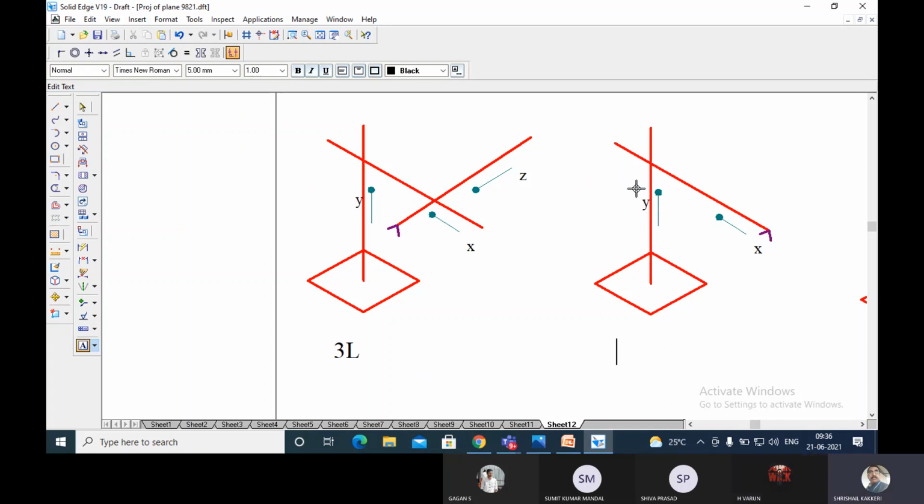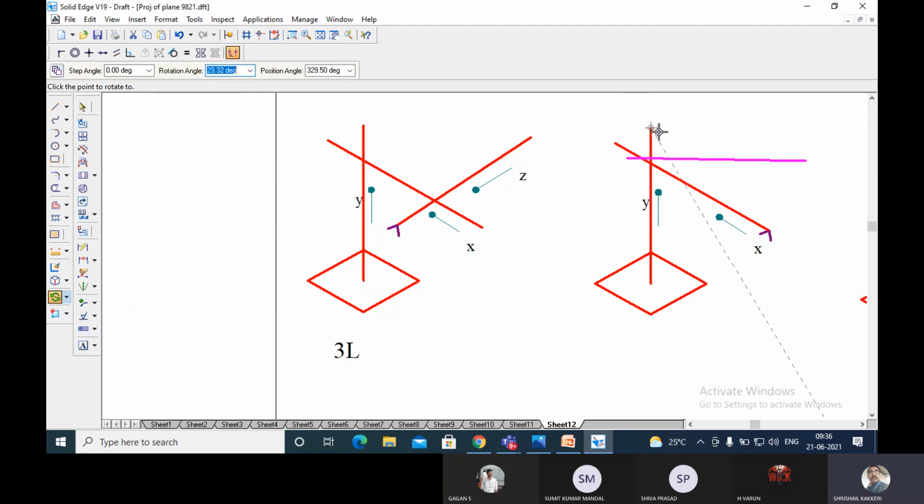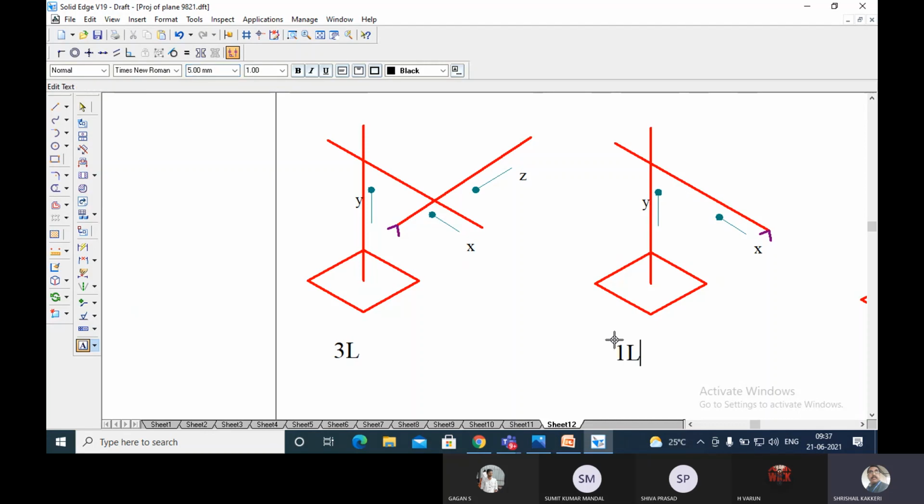Yes, sir. It will be linear movement, and this will be rotation here. This arm can be rotated like this, about this point. You understood my point? It can be rotated. This arm can be rotated like this, so that it is a rotation along this axis, and this is the retraction, and this is moving up and down, so this is called a 1L and 2R robot. Correct?